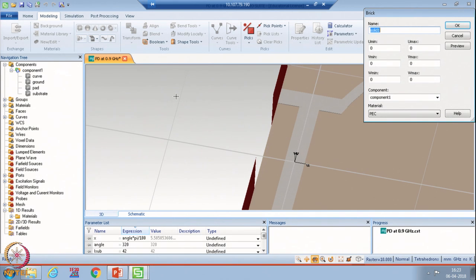So, in our case, this resistor that we will be using is 0603. So, for 0603 resistor, the length is 1.6 mm and the width is 0.8 mm. So, accordingly I will cut the patch from this microstrip pad. So, in U, length will be same, and then V, maybe just take the variable name LSMD by 2.